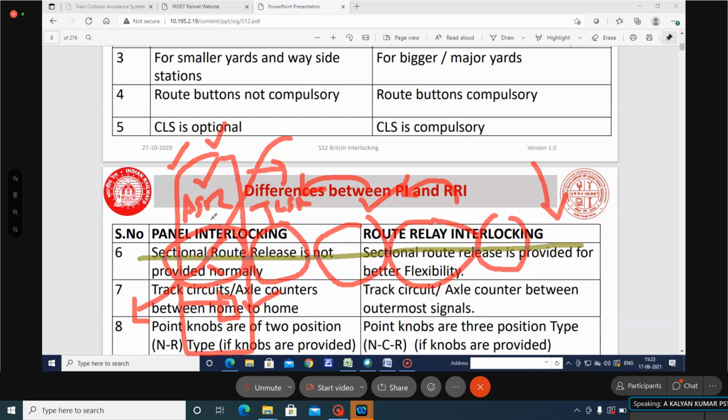So why am I interested in only backlocking tracks? Why am I not interested in berthing track? I am going to pick up the ASR only when all the backlocking tracks are in up condition. So why only backlocking tracks? Why not all the controlling tracks? Backlocking tracks have the capacity to make the route change. Yes. So once the train has passed the last point in the route, there is nothing further to change it. We are not going to change the route further.